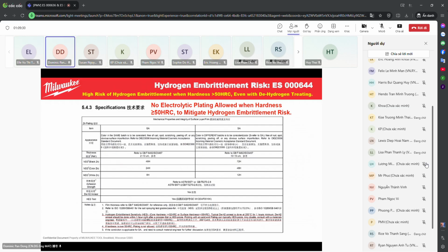Here we are about surface treatment. For powder metal parts, maybe it's not a big concern, but for other steel parts there is a big concern, so-called hydrogen embrittlement failure. What does it mean? It means the parts, especially those with thread structures, can break or crack without any usage, only after assembly in line. After 1 to 7 days, they can crack or break without any mechanical loading. That would be a huge trouble for us.